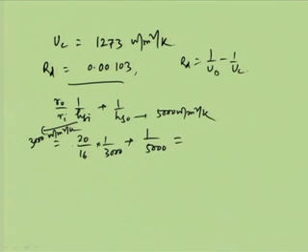This value gives me 0.000617 meter square Kelvin per watt, and my RD value has come to be this value in meter square Kelvin per watt. So, it says that the estimated RD is well above the possible RD for this process.